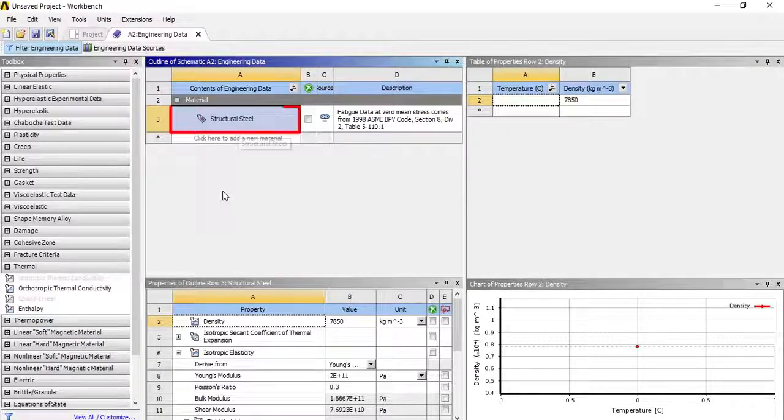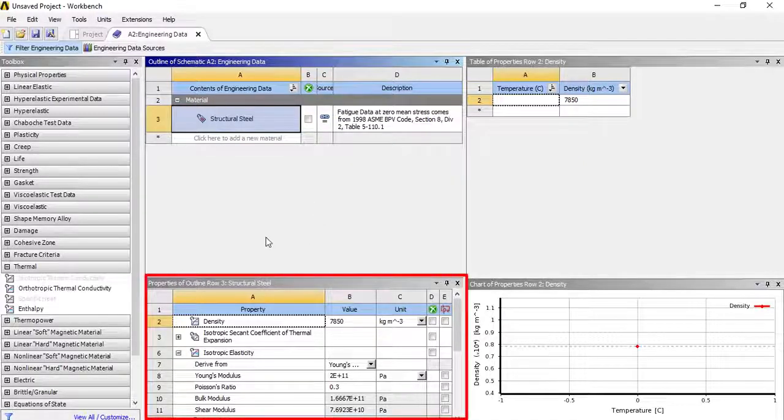In Ansys Workbench, structural steel is the material that is always defined as a default. So if you just open Ansys Workbench and don't define any other material, then the project will be assigned structural steel by default. Here in this particular group, you are going to see all the materials that are available for the current analysis. Right now, as we can see, only structural steel is available. Then this shows the properties of whatever material we have selected.